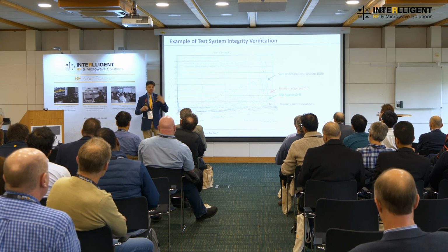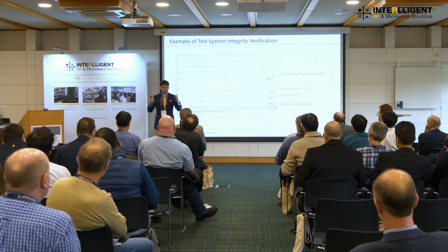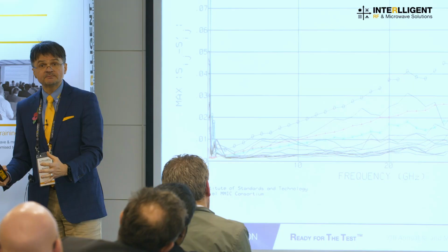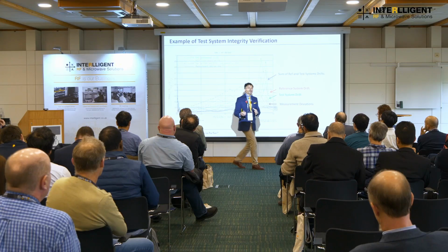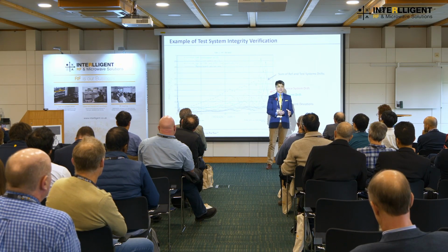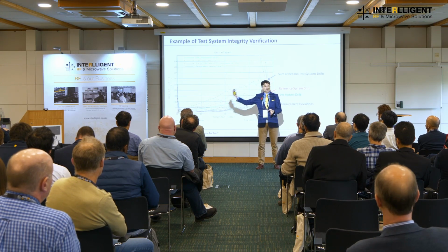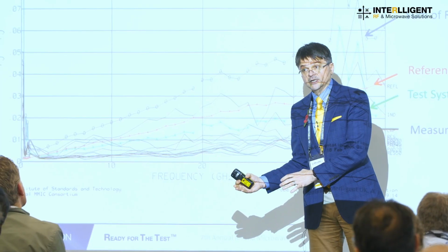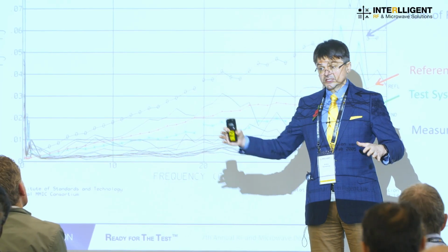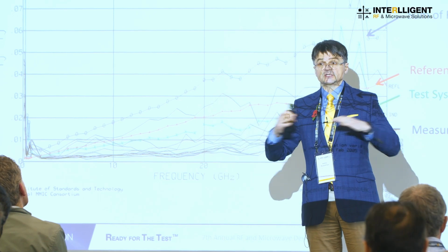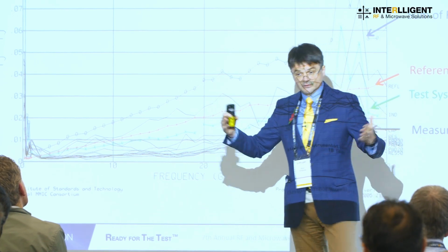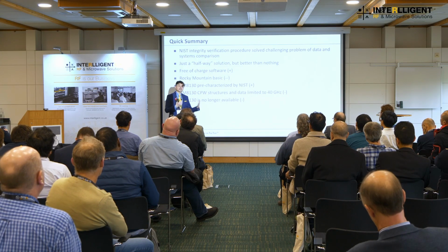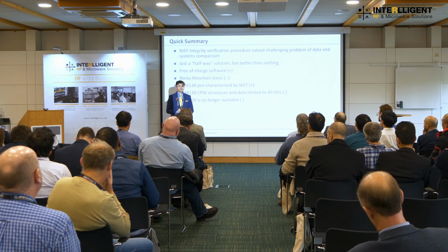They computed, and proposed to compute, the experimental drift between two sets of the calibration error terms. One is acquired at the beginning of the experiment, and for the other one, you recalibrate your system at the end of the experiment. And you look into the difference in these error terms. Of course, they're different if your setup has drifted. If your setup was absolutely constant, the difference between these two calibrations is like a unity matrix. But we live in the real world, which means that every setup we do measurements on drifts during the experiment, and that's important to quantify this drift.